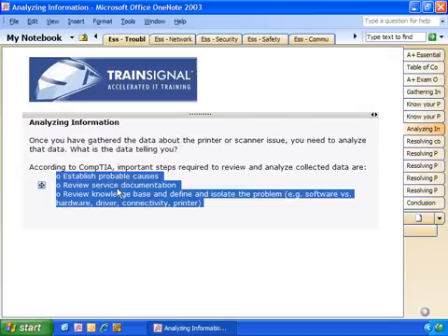Periodically, yeah, you change the oil, but at 50,000 miles, you have your major service done where the car is taken apart, the belts are analyzed, the air filters changed, all the parts are lubricated, so on and so forth. They have this long list of things that has to be done at this major maintenance interval.